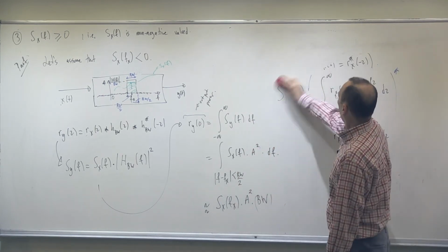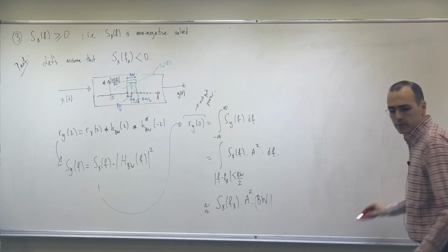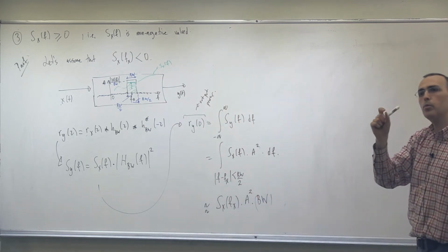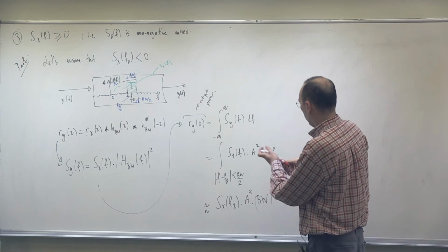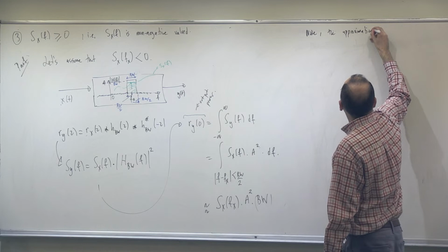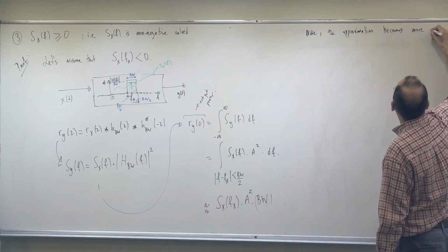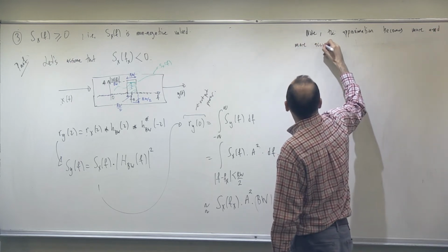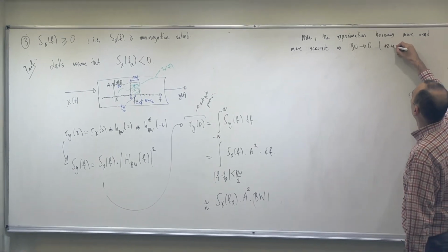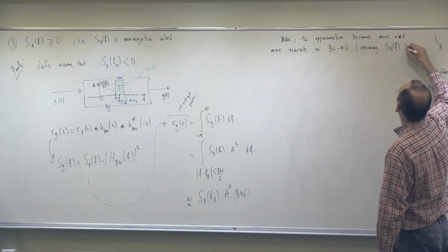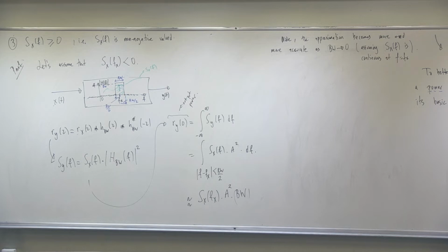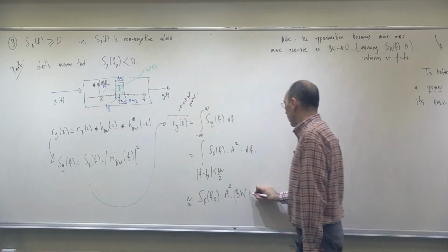Let me write that as a comment. As I have said, this is a free variable. There are no constraints on my bandwidth. I can make my bandwidth maybe 1 hertz, maybe 0.1 hertz, maybe 0.0001 hertz. So it can be smaller and smaller. Note, the final approximation becomes more and more accurate as bandwidth gets smaller, assuming, as is almost always the case, that Sx of f is a continuous function, continuous at f equal to fx. There are some details like that, but intuitively we got the feeling, I guess.